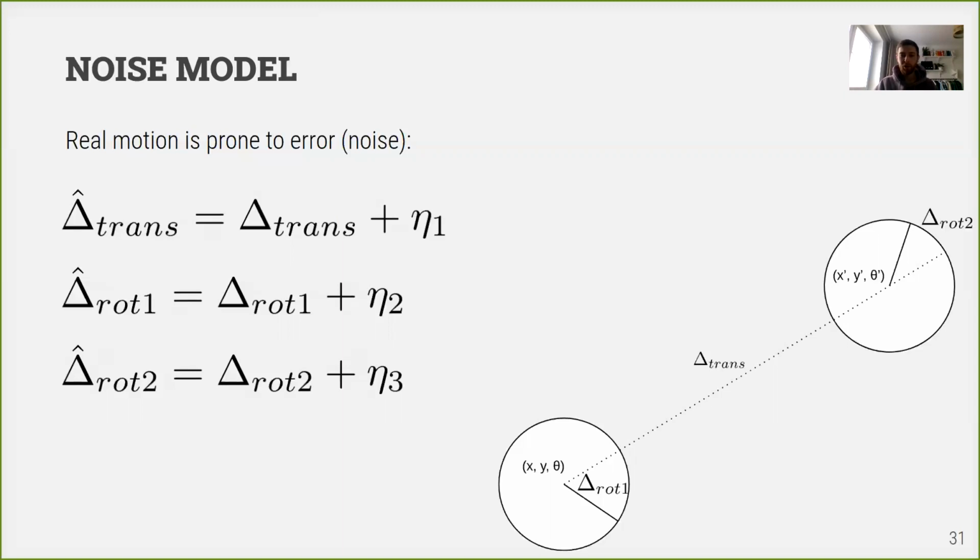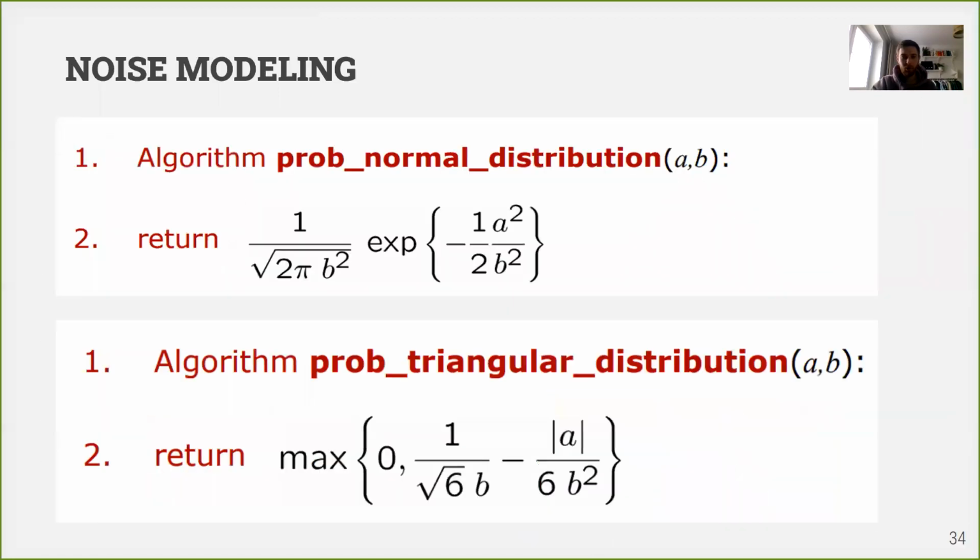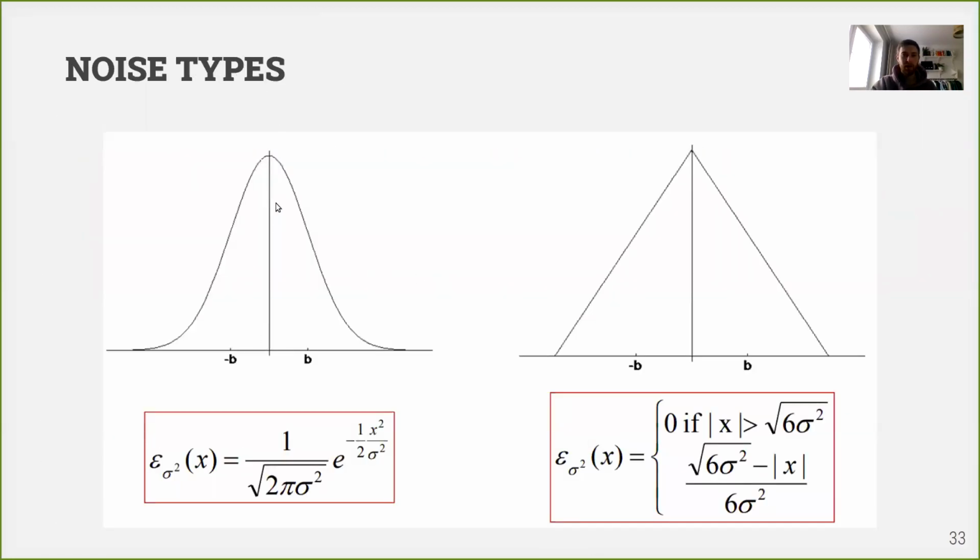So basically, if our encoders are saying that we traveled 1 meter, we will have a normal distribution with a mean of 1 meter, and also some variance, and variance depends on our experience. So if we know that our motors are quite precise and the world we are operating in is quite flat, quite simple, without any external factors influencing our motion, then the variance can be small, because we are quite sure that if we are commanding the robot to move 1 meter, it will move 1 meter or something really close to 1 meter.